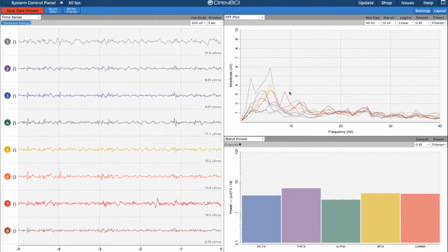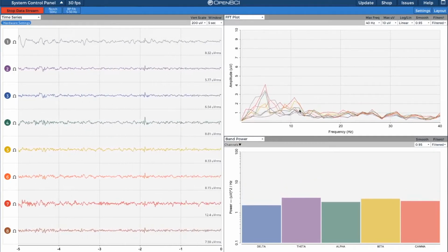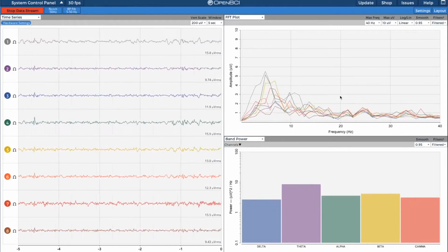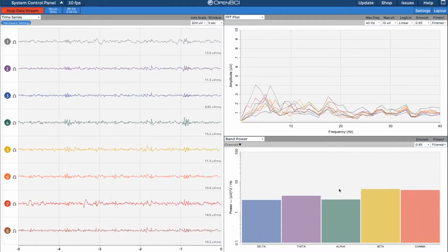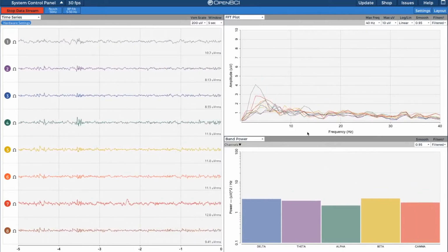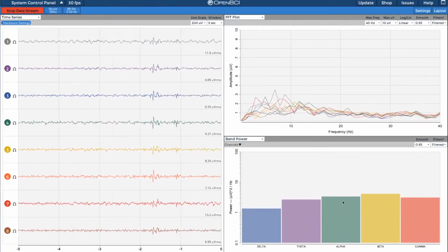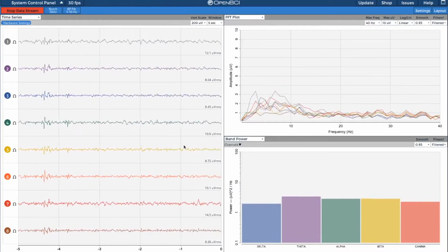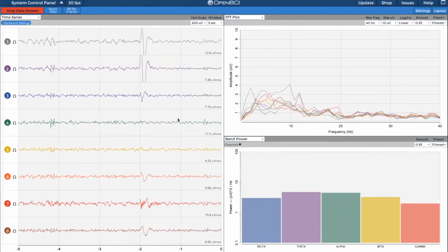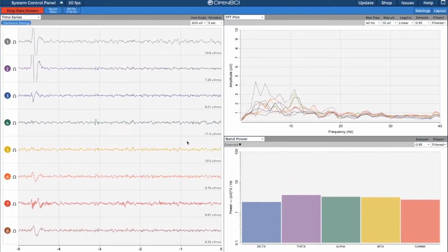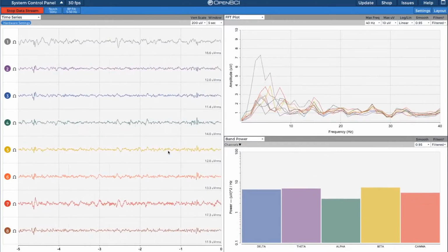For a very general example, your brain might be producing beta waves when you're in a normal waking state, although when you're more focused, it might produce more alpha waves, which are those 12 hertz things that you saw rising before. And this is kind of what's going on here. Right. And that's actually what we're going to use to build our first BCI system. So we're going to try to make something that picks up whether or not you're focused by judging the differentiation between your alpha waves and your beta waves.